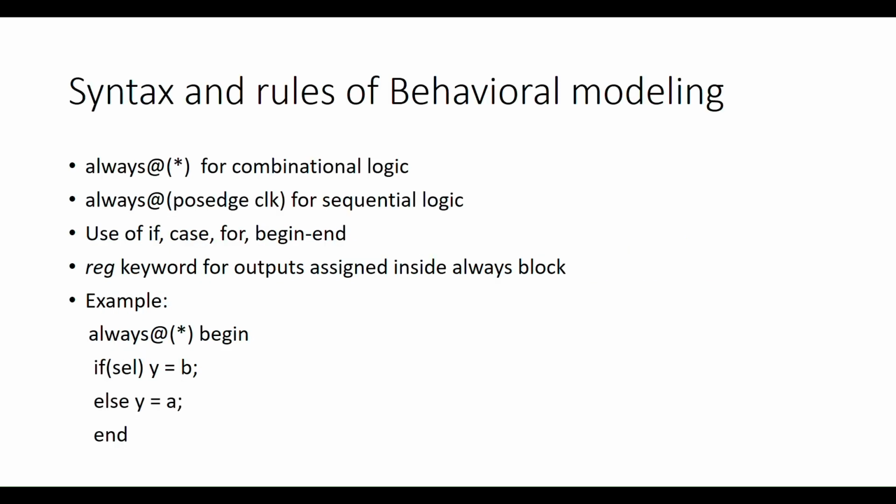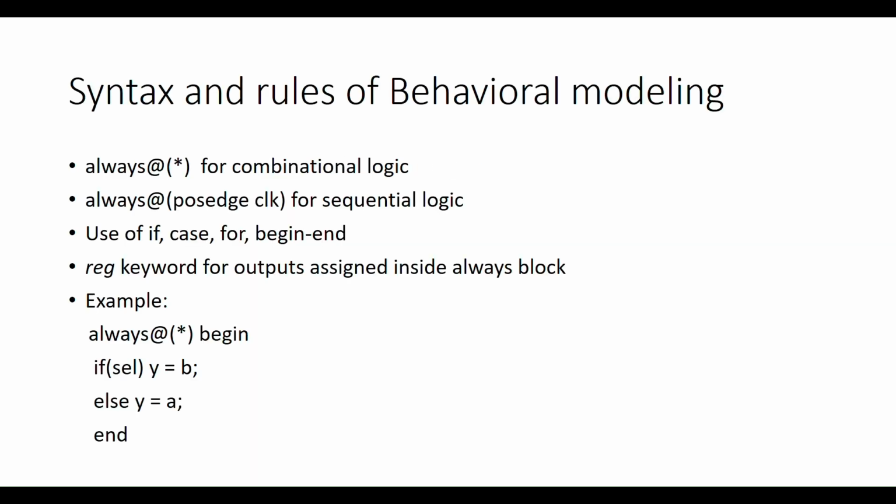These are the syntax and rules of behavioral modeling. We can use always blocks for combinational circuits and posedge clock in an always block for triggering in sequential circuits. Use if, else, case, and begin, end. A reg keyword is used for outputs assigned inside an always block.